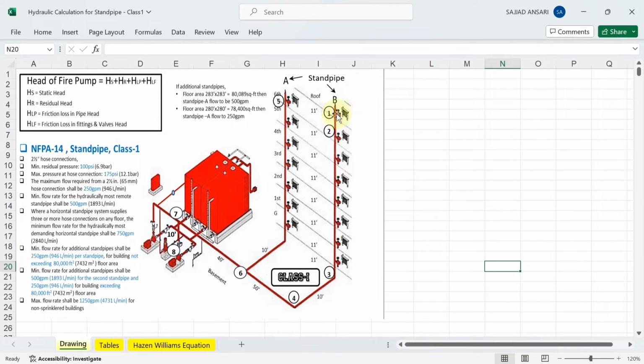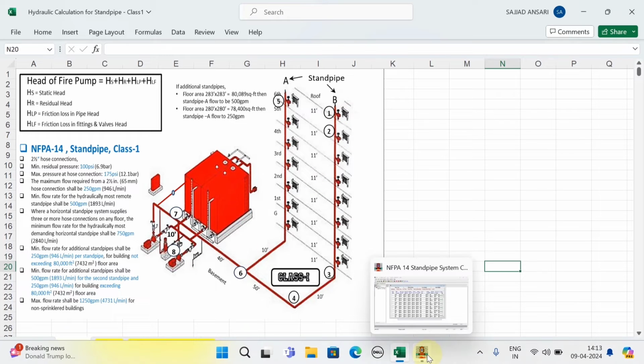We are talking about the 1 to 2 path, so at that time only one hose connection will come in. So 250 GPM from each hose connection, 250 maximum flow rate. So flow rate is 250 GPM at node 1 to 2. And for this hose connection you have to consider a 2.5 inch gate valve as well. So come and fill the detail.